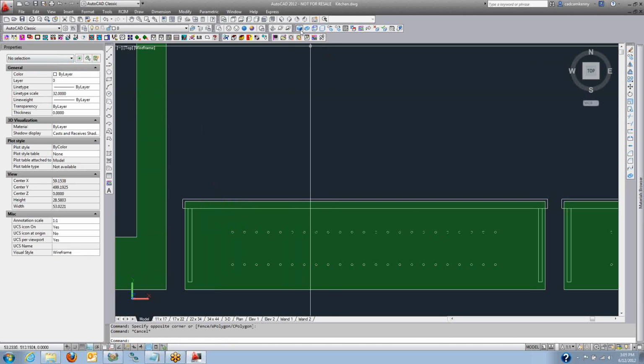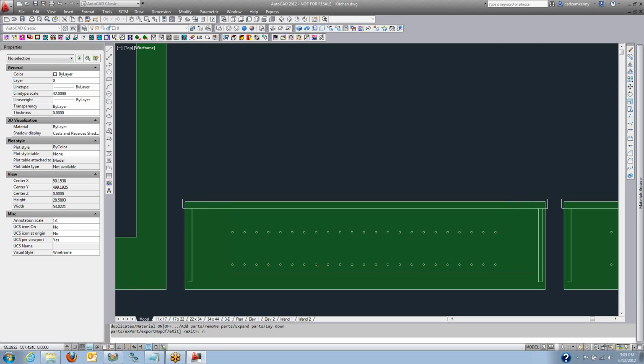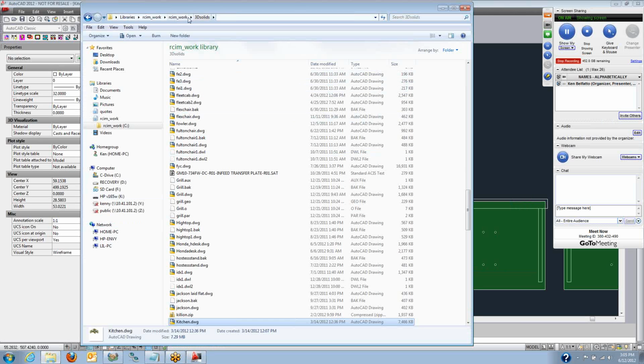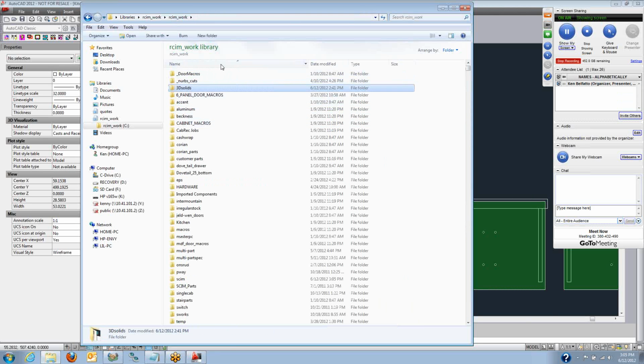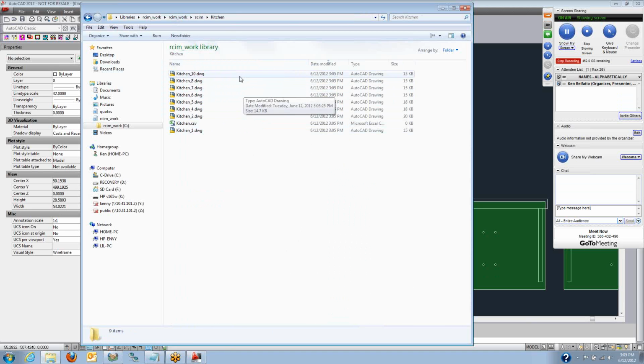So now what we do in Solid-CIM is we export all the parts, and this will create a CSV file that's a cut list of all the parts. So we go into the export button. It's going to create this CSV file for us. At this point, all of the individual parts are exported into a folder, and we can actually see that folder being created. Here's the folder with today's date and time as the parts are populated in here, and the cut list is created as well. So all those parts are being exported.